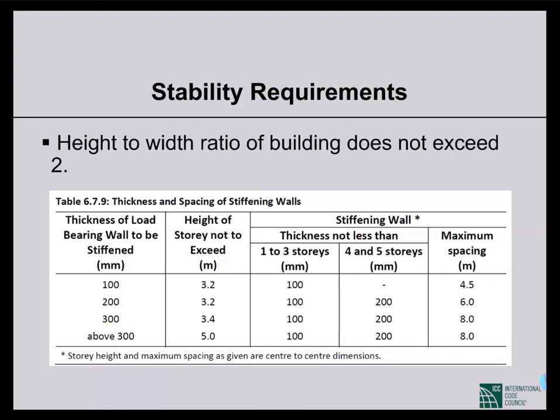What will be the modulus of elasticity of masonry wall that is given? Em equals 750 root over Fm prime, in megapascal, if you express Fm prime in megapascal. Fm prime is the 28-day masonry strength that you get from the prism test. So 750 times root over Fm prime is the modulus of elasticity.